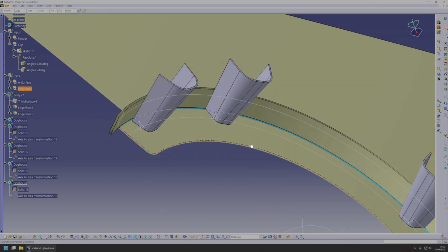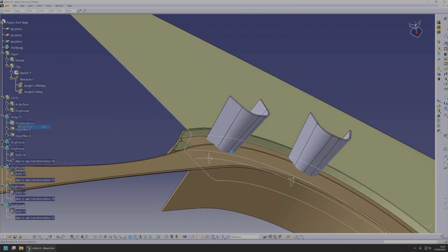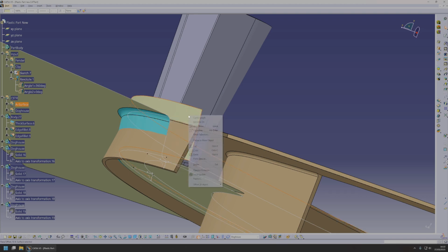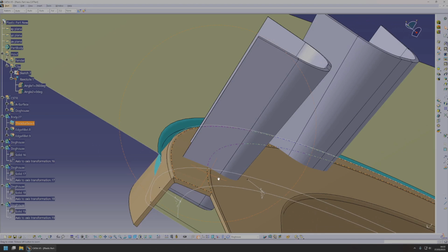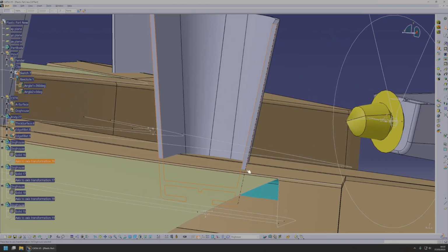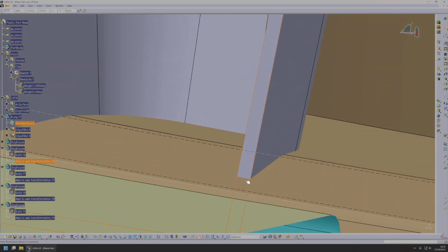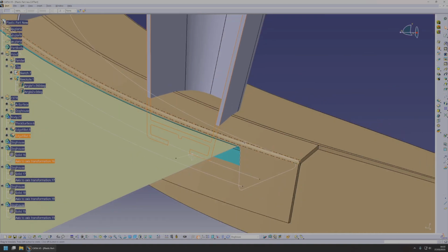Right, but are we happy with this? No, we are not actually. Because I don't know if you've seen any parts and how they look, but the doghouse here, when it meets the surface, has a thinner section here. Why do we have that? That is due to surface sink.